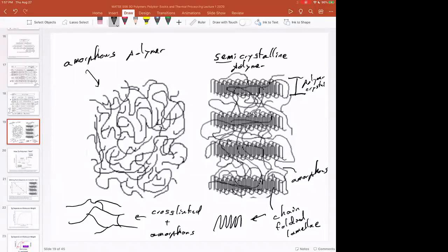Oh, I see a question here. The opposite can be true though, right? Some polymers can be 100% amorphous. Yes, of course. There are some polymers that don't crystallize at all and never will. That's also really interesting because, of course, with metals you can have amorphous metals or bulk metallic glasses. But if you process those a different way, of course you can get metals to crystallize.